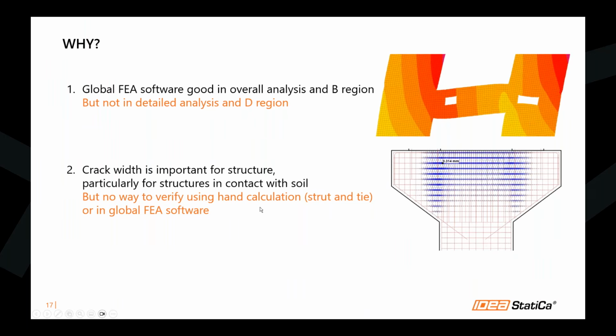But currently there's no way to verify this crack width using a hand calculation like strut and tie. It will only give you a ULS result, but not the SLS result. Also, in your global FEA software, you will not be able to find the crack width result. I'm talking about ETABS: for walls, you will not be able to find the crack width result. But of course, in IDEA StatiCa Detail, you can find this crack width result, as you can see here in one example of our output.